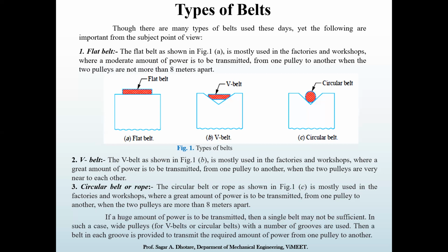If we increase the number of grooves and the number of belts, for example with two grooves engraved, so two belts, each belt carries 4 kilowatts. As we need to transmit 8 kilowatts, it is divided, and the life of the belt also increases. So in this manner it works.